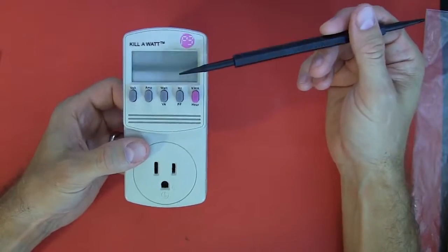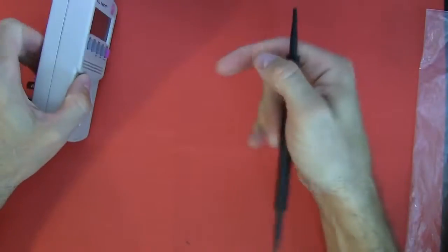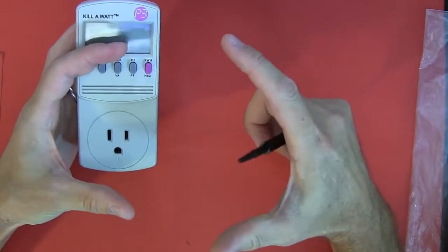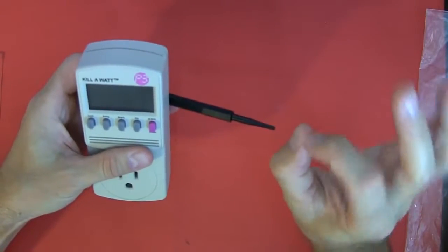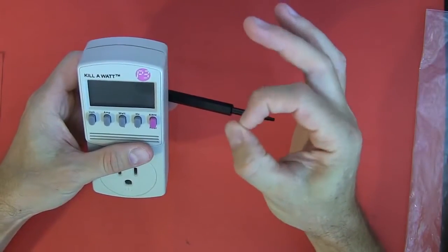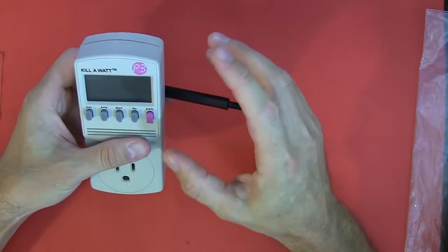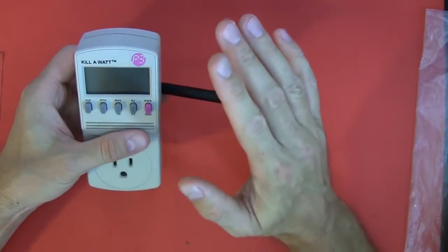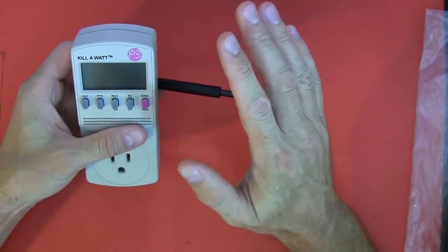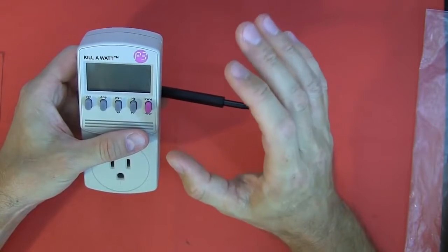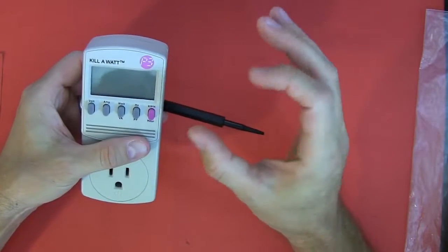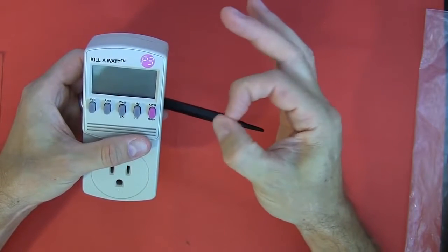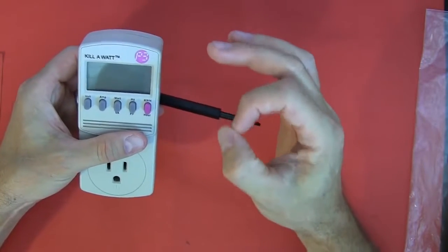So what you can do there, and again, that video I told you about, you can buy the cheaper devices like an OWL or an Effergy. There's quite a few of them now. And those you need to actually clamp round the individual circuits in your DB board. So that gets a bit more tricky because you need to know what you're doing. You need to be qualified. I certainly don't recommend that you open up your DB board unless you know what you're doing, because it's very dangerous. But a qualified person who would potentially come and do an audit on your house could put these current clamps or current taps around the individual circuits to measure what each of them is actually producing.